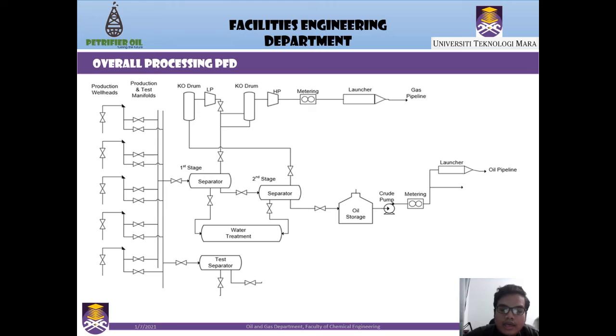And as for the gas, there's a need for gas processing units or equipment, so that the gas could be handled safely, and the gas that needs to be flared shall be flared, and the gas that should be processed or stabilized will be stabilized and processed. All these are required because before the processed hydrocarbons could be transported to the Labuan terminals, the hydrocarbons themselves need to be processed to meet the requirements of the Labuan terminals.